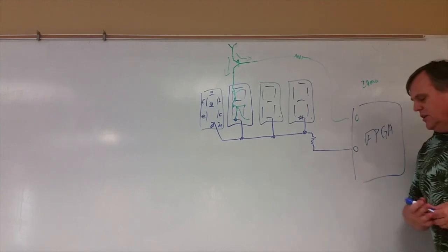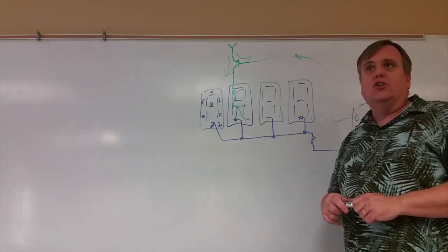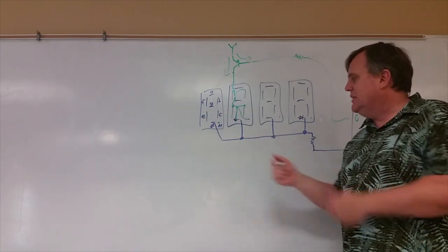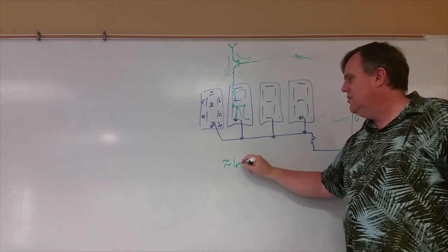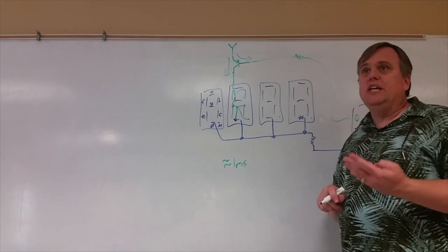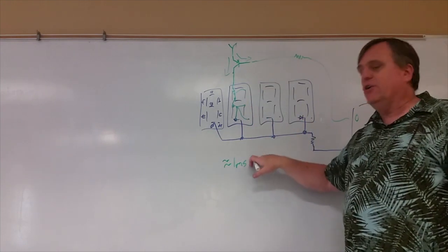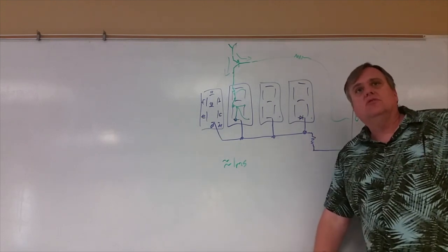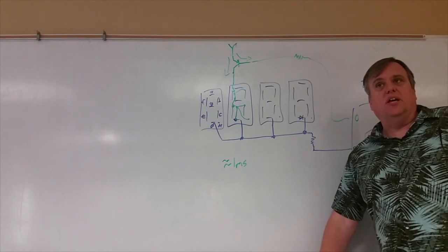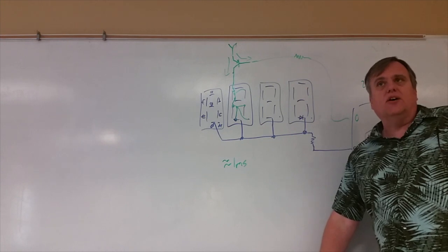Well, let me do this. Now I need to be able to switch between them at a reasonable pace. So that means I need to find some way to get this in about the millisecond range. So what you need to know, anybody know a way I can figure out how long a millisecond happens? Look at the clock cycle. Okay, I get clock cycles. My clock cycles are happening in the megahertz range. On ours, I believe it's 100 megahertz.